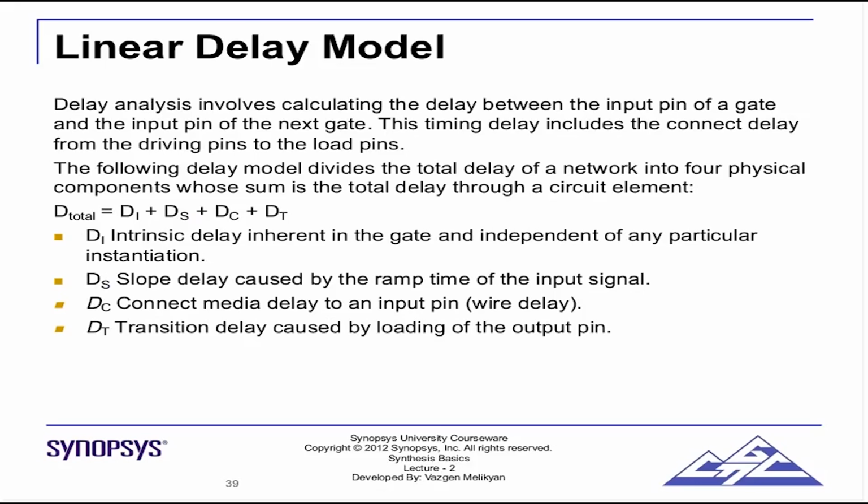Therefore, this timing delay includes the interconnect delay also, from the driving pins to the load pins. The linear delay model divides the total delay of the network into 4 physical components and sums them up for the circuit element. So the total delay is Di plus Ds plus Dc plus Dt. Di is the intrinsic delay inherent in the gate.